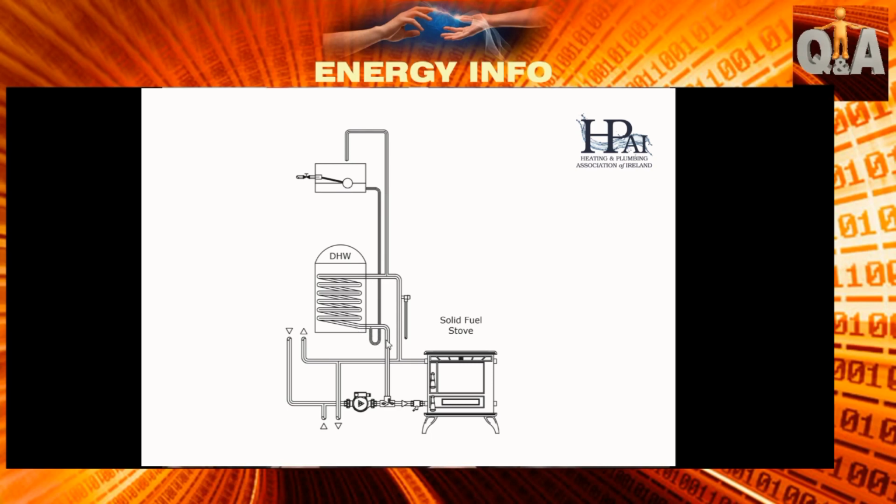But on the injector side of the system, where the pump is pulling water from the system, it shows here where there's a downstairs circuit and an upstairs circuit. The pump is pushing it through an injector T, which is a narrower piece of pipe within the T. As it pushes through, it causes a vacuum above the centre of the T, which pulls the water down from the cylinder, and it fires the pumped water through the boiler, but also induces a flow on the gravity circuit through the cylinder. So an injected system, very good, normal systems, highly recommended by most boiler manufacturers.